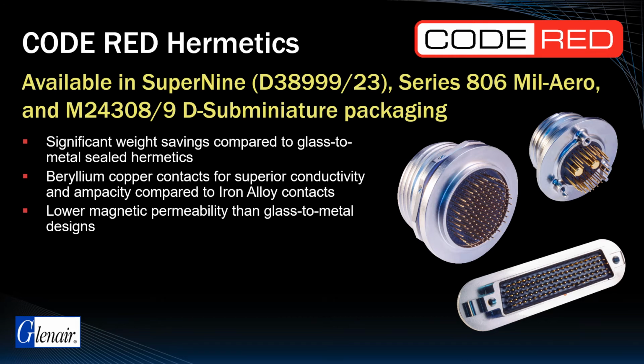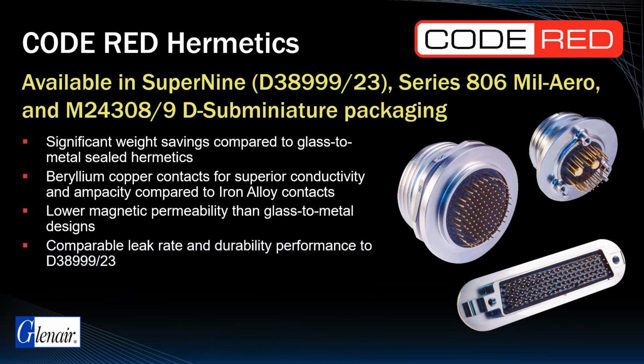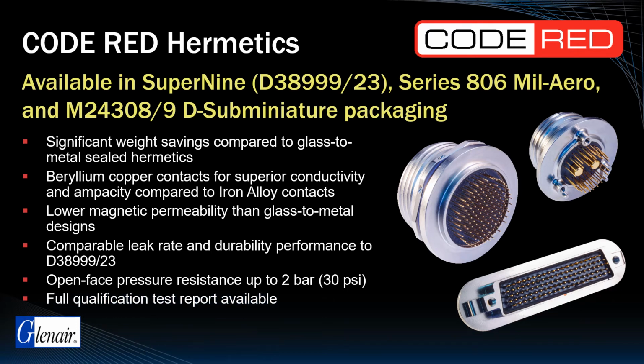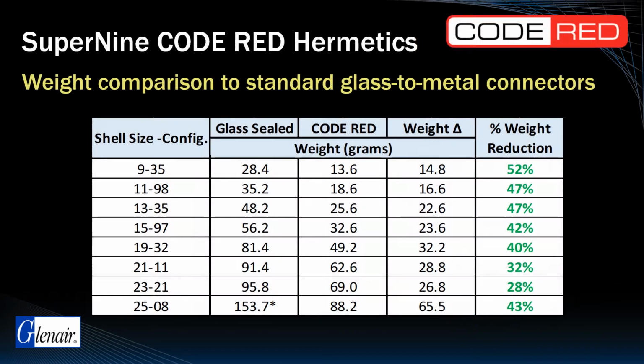As stated previously, CodeRed delivers comparable leak rate and durability performance to D38999/23 configurations. For subsea applications, CodeRed has been open-face pressure resistance rated to 2 bar or 30 psi. Full qualification test reports are available. As promised, CodeRed is significantly lighter than conventional glass-to-metal seal designs.